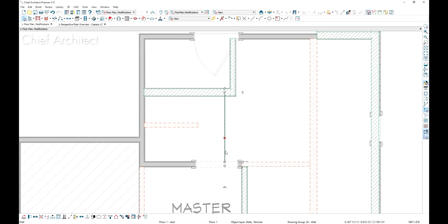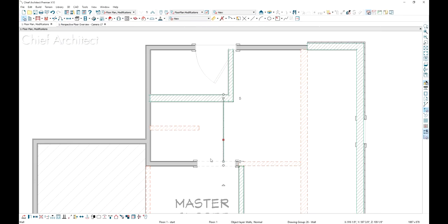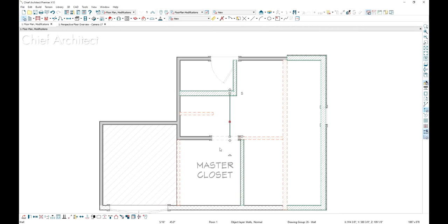And then we'll position that into place. And then finally, let's go ahead and remove the different doors that are in the plan. We'll just go ahead and delete this one, and there's one more down here. And let's go back to 3D and take a look.